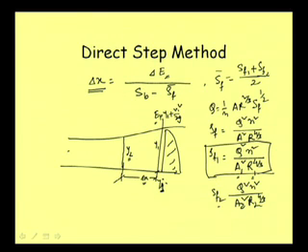So this y2 we are considering from our side, and we want to know what will be the delta x, or at what distance from y1, that is x1, suppose this one, and this is suppose x2, at what distance from x1 this x2 will be, which corresponds to depth y2. So taking this y2 as our known parameter, we are calculating SF2 and we are calculating E2. So everything we are calculating, and then we are calculating what is our delta x.